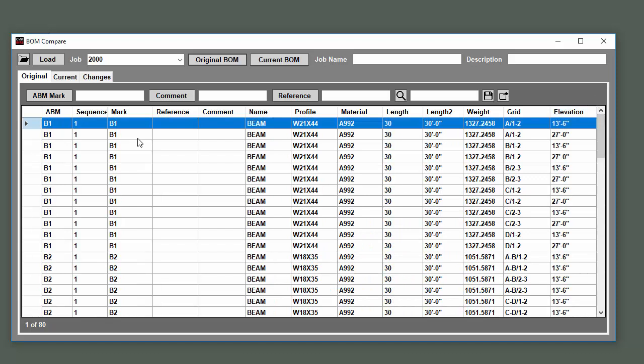and now it has been imported here into the Bill of Material Compare project. Now here's what's really great: if you don't have a robust material management or production control software like FabSuite or FabTrol, as an example, then at a very basic level, you can add references in here. So if you wanted to keep track of your purchase orders, like if you're the project manager or the purchasing agent for a fabricator, and you want to keep track of a PO or mill order reference or something like that, you can select that in here and apply that.